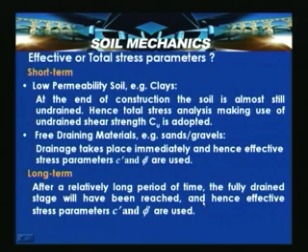For the long term conditions, after a relatively long period of time, the fully drained stage would have been reached, hence the effective strength parameters C dash and phi dash are used.